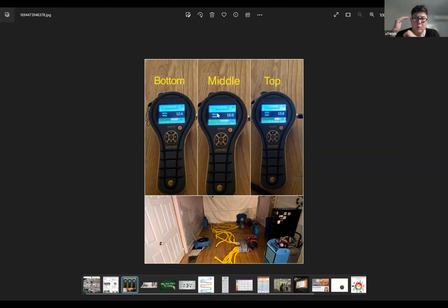He's trying to see if there's any bound moisture in it. Water on the top surfaces, the boundary layers, always dries faster, because you might have some fans that come in and it's exposed to aeration and circulation, so this is drying much faster. And the bottom of the material might be the same, in that it may be on a substrate and there's ventilation underneath, and the moisture has either not penetrated all the way through or is drying faster.